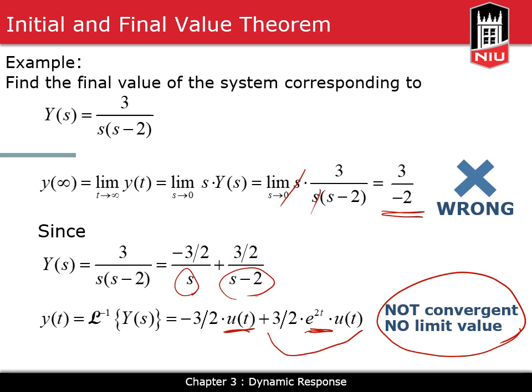Now you might think, what is the point of using the final value theorem if we have to apply the inverse Laplace transform and check our answer? If we apply the inverse Laplace transform, we can easily let t approach infinity, find the answer, the final value of y of t. The answer is, we don't really have to apply the inverse Laplace transform to find out whether the signal is stable or not.